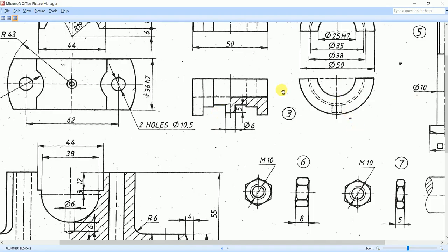As can be seen here, it has an inner circle and an outer circle, and it looks like a cylinder. Therefore, this particular component is a hollow semi cylindrical component. So we can create this hollow semi cylindrical component by using the revolve option.